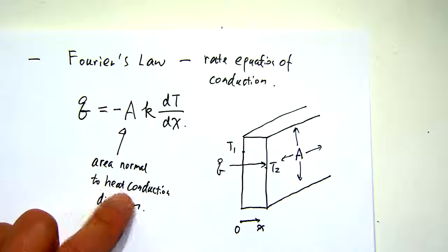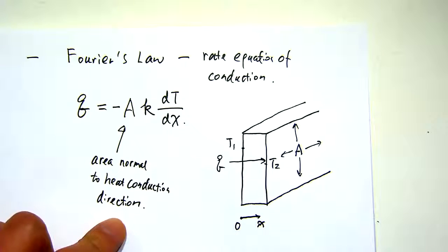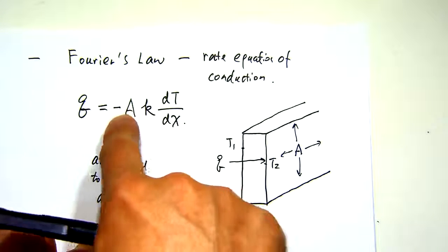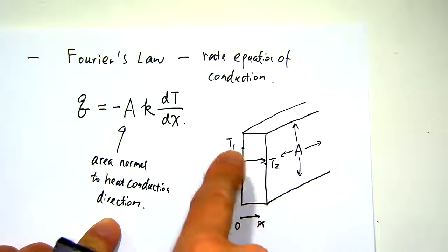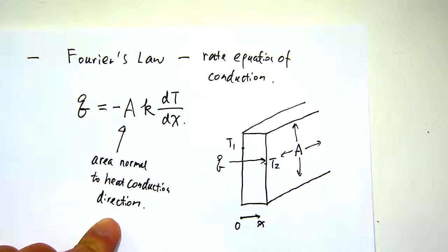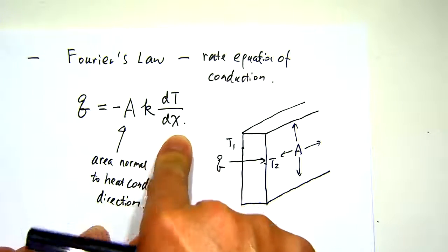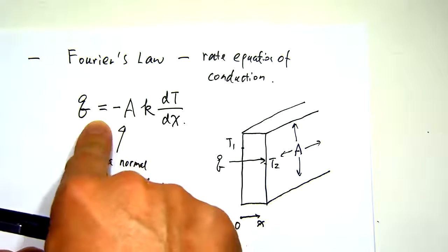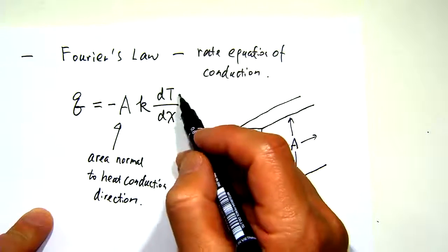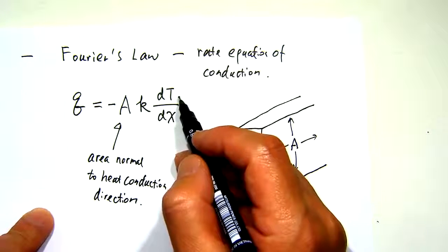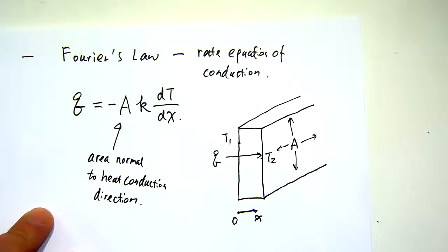We know the heat conduction, or the heat transfer, always goes from the high temperature to low temperature. And this negative sign there actually is to correct the heat transfer direction so that we constantly have a positive value. So if you're looking at why we have a negative sign there, the heat transfer is going from the high temperature to low temperature, so this dT is always negative, right? Always negative for the heat to be transferred.